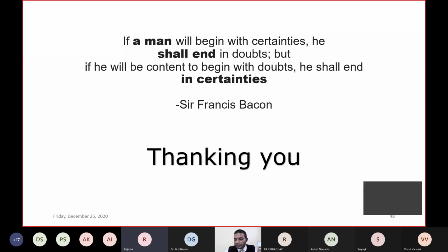So what solution did we give? Because in remote areas you don't have any equipment or agencies to provide solutions. In our department we have standard designs for different bearing capacities of soil, I mean the foundation of the reservoir, for different staging heights and different strata. Generally, the strata whenever we meet with BC soil is 5 ton per meter square. Even for a depth of say 3 meters, we don't add the overburden into that. We adopted 5 ton per meter square as the bearing capacity, put the raft there and started our construction. It worked out well, no problem till today.